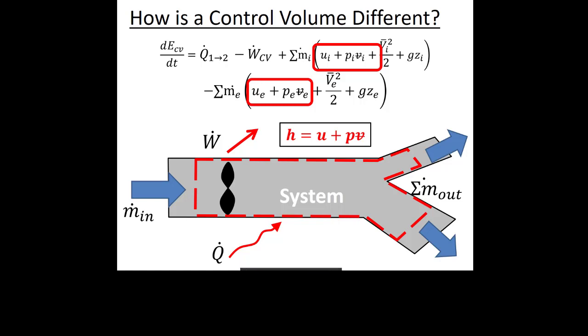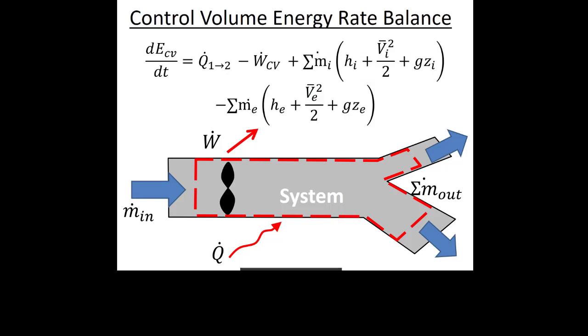Now, we talked about how specific enthalpy is on the tables that we look at, but we never really talked about why. And the reason why is so that we can be more efficient when we're trying to fix the states here, so that I don't have to find specific internal energy and specific volume at the same state, when once I know one of those things, I'm probably going to know the other one automatically. So why not combine them together, and that makes our lives easier.